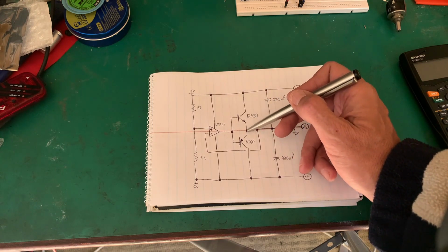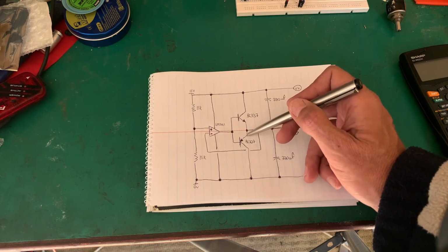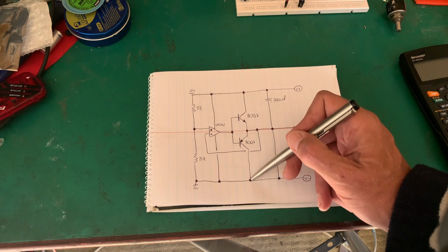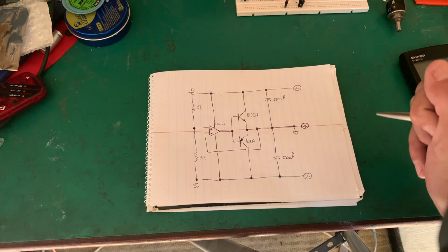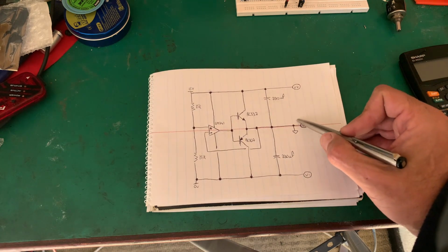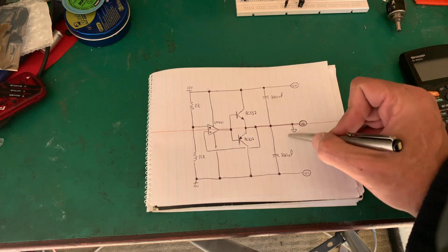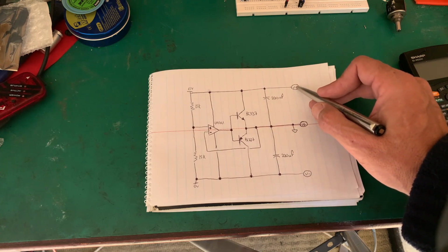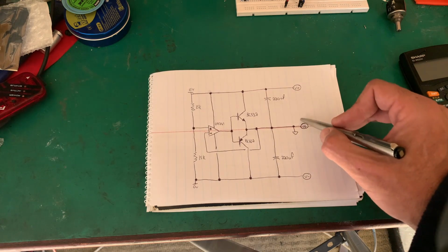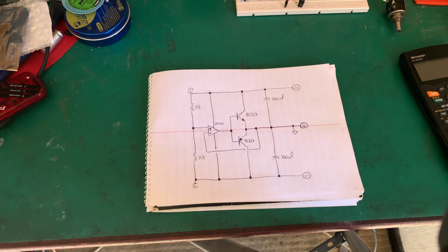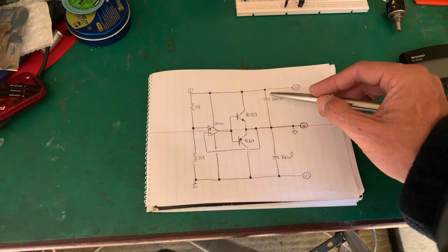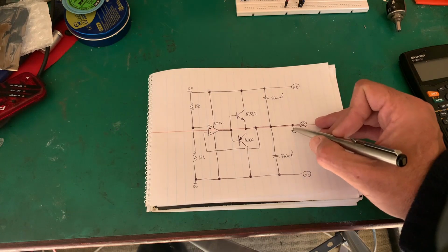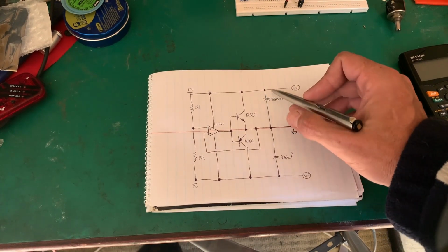So we're coming through our transistor to this middle rail, and this transistor is pulling that middle rail down. We have two capacitors here, just some bulk storage smoothing, and here we get this thing. So we have a plus V, now all of a sudden a minus V, and this thing a VG, virtual ground. Remember we spoke about that virtual ground? So what effectively we've done is we've divided this rail in two, so 15 volts to 7.5 volts.